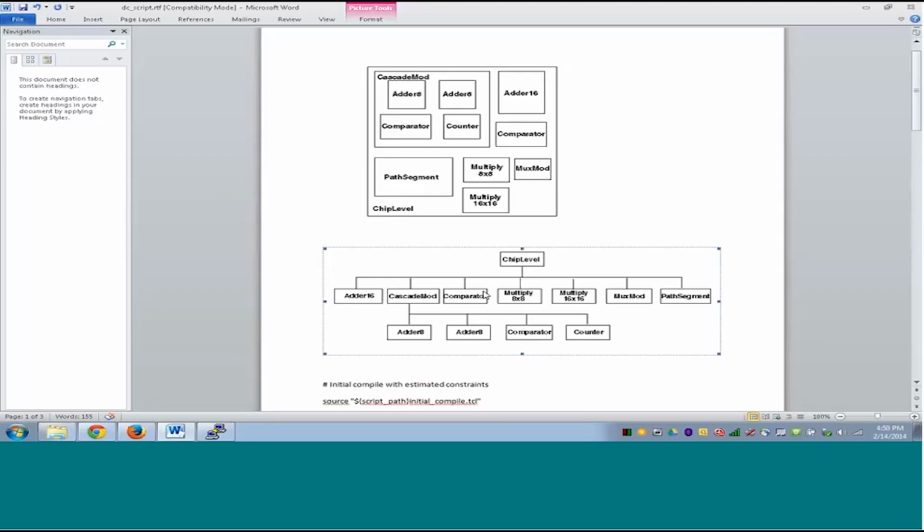So what we do at chip level in the industry, let's say the blocks are HDMI, USB, and CPU. Each design team will carefully write constraints for HDMI, USB, and CPU. There will be separate teams working on these, and one person from each group will spend a lot of time making sure the constraints are okay. These constraints will never be characterized by DC, they are owned by the user, generated by the designer. So the designer will work on the constraints.